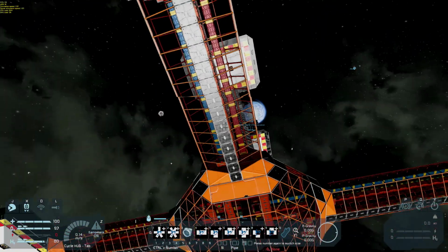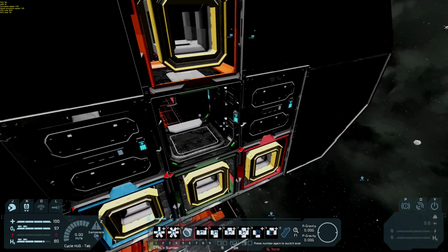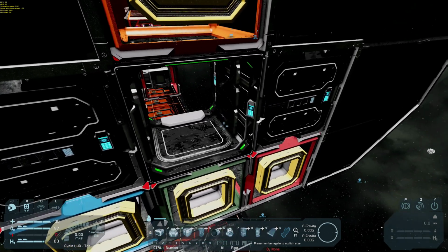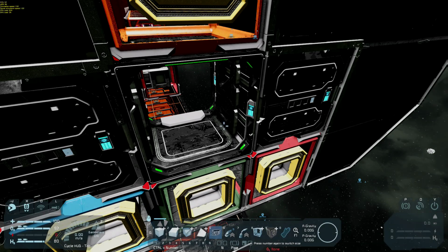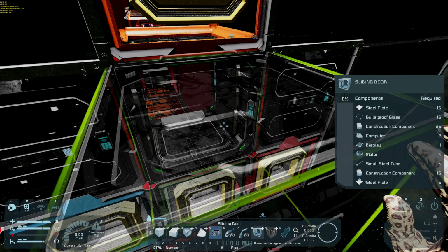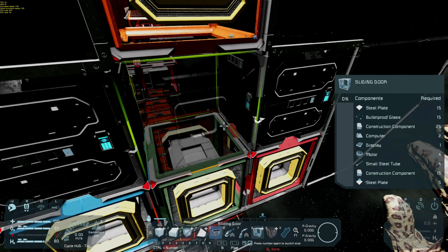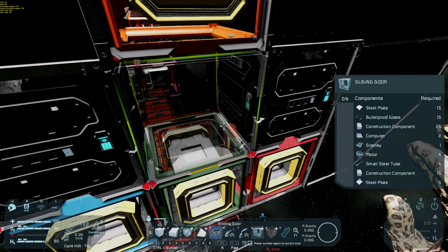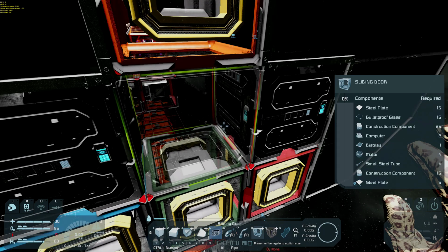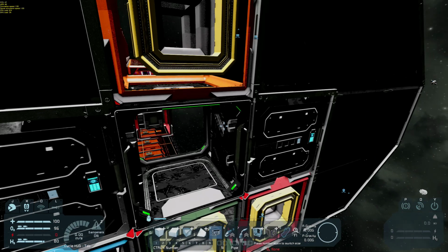Because in this case, everything is on that side. So what I think I'm going to do in this case is take the door out. The door is black, so we're going to recolor as black. Okay. 8 is our door. We're going to delete this door. We're going to create a new door. Hello, where's my door? Okay, there's our windows, and that is actually the side I want it to be on. So I want it to face, in this case, the room side.